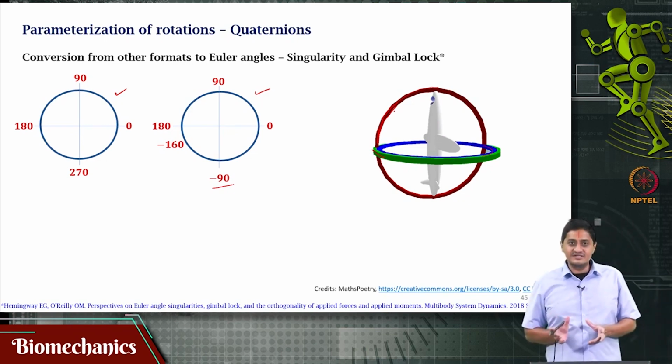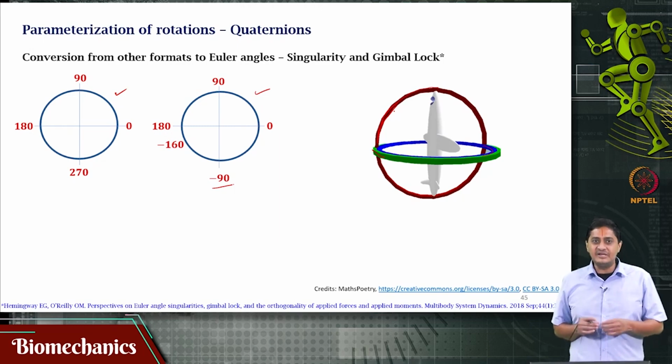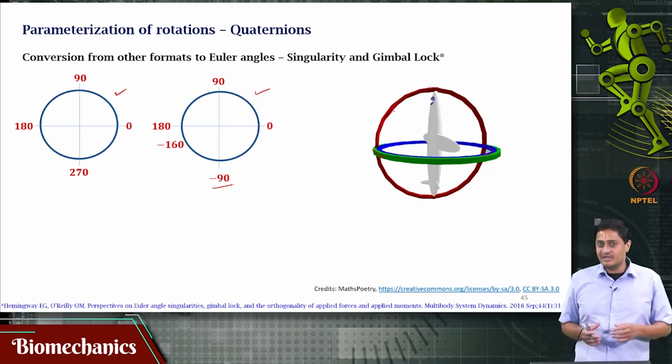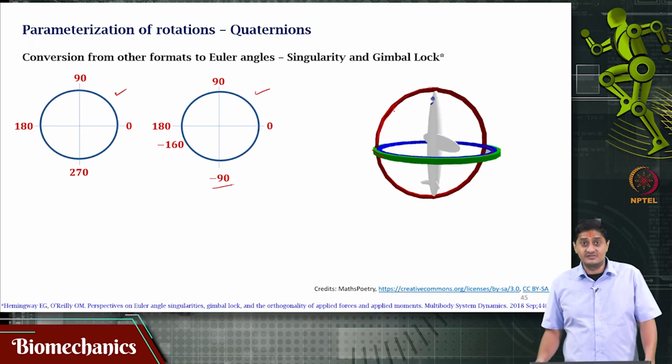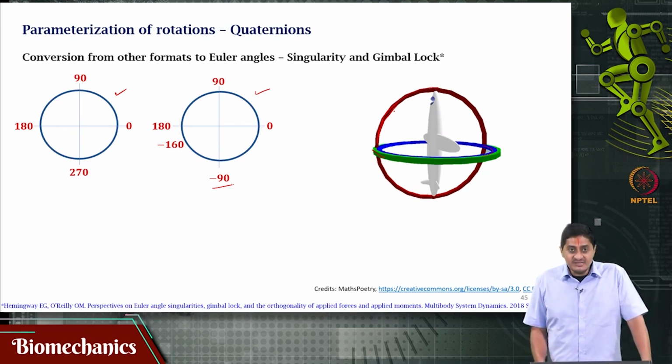This made the entire inertial measurement or orientation system completely ineffective. So, for some time the spacecraft did not have an idea of where or how it was oriented. This is a dangerous situation. For this to be corrected, it required that the spacecraft be pitched away from these locked situations, and then recalibrate the gimbals by using the stars as the reference position.